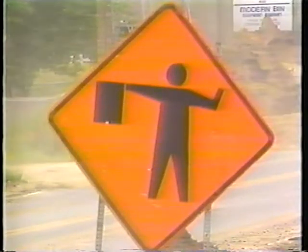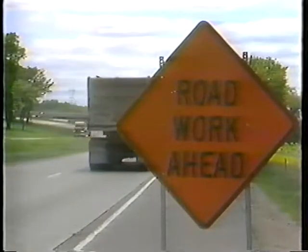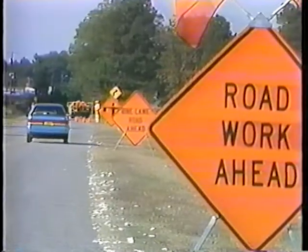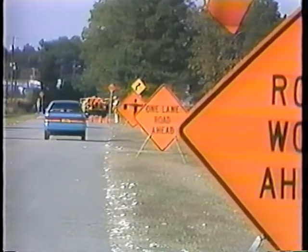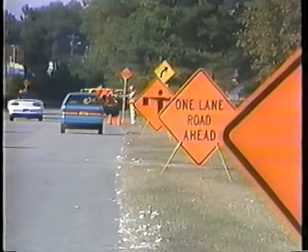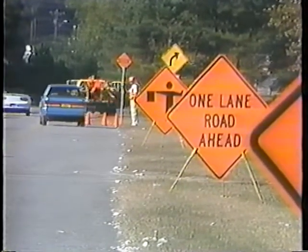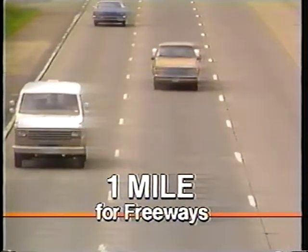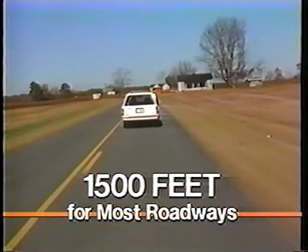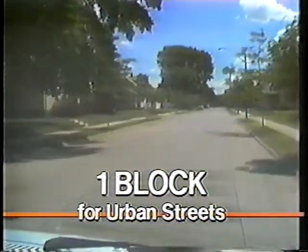In the advance warning area, traffic control devices may vary from a series of signs starting a mile in advance of the work area to a single sign or flashing lights on a vehicle. The advance warning area, from the first sign to the start of the transition area, should be long enough to give the motorist enough time to respond to the control devices. For most operations, the length can be 1 mile for freeways or expressways, 1,500 feet for most other roadways or open highway conditions, or 1 block or more for urban streets.